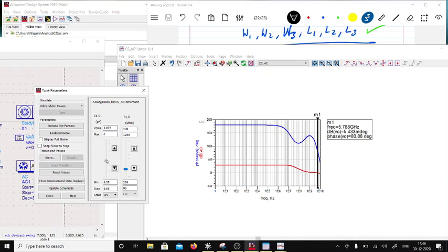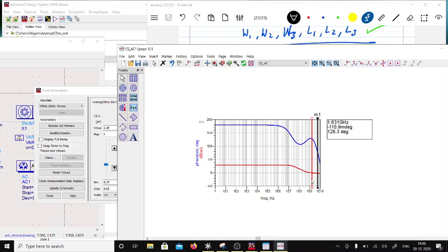I don't want to do very large capacitance, but if I want, I can do that. I hate that. And reducing the resistor also basically changes things. So I am here. Now I have enough margin. This is minus 90. So this is the zero. So now I have 129 degrees margin over here.